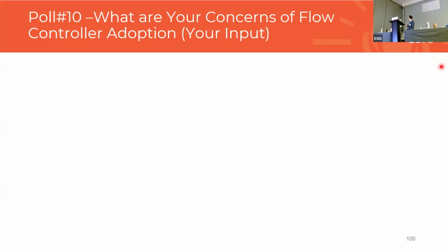And I know one thing that the manufacturer points to as somewhat of a benefit is that because it is shunt connected, when it does fail, it fails to what they call a normal operating condition. So yes, you lose the benefit of the device, but if a car runs into it, it's not an outage per se. You've just lost the benefit of what it was giving as a device balancing the system.